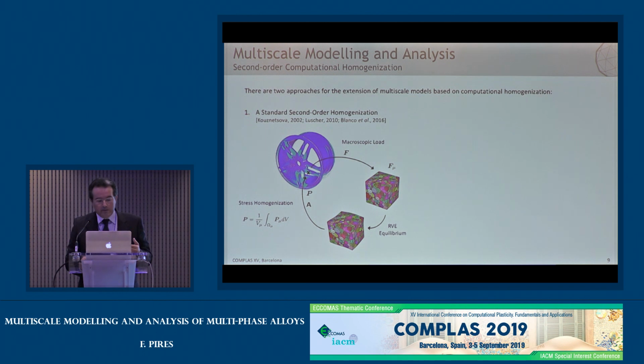And the normal course of action in the analysis is basically we prescribe to a macroscopic point the first deformation gradient and the gradient of the deformation gradient to a microstructural volume element. Every microstructural constituent is actually modeled with a classical continuum, and the RVE problem is formulated in terms of standard boundary conditions. And from the solution of that microstructural boundary value problem, we actually can compute the macroscopic higher order stresses and also the tangents that we need to run a fully coupled FE square simulation.